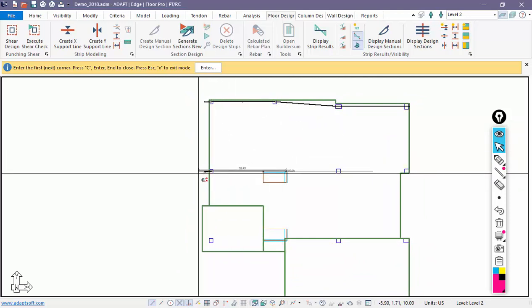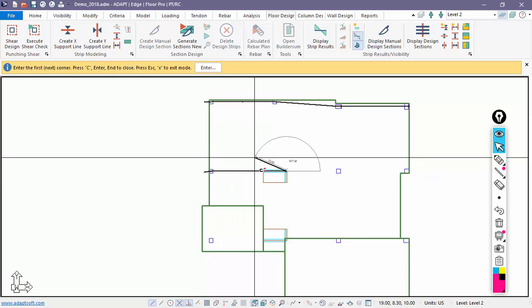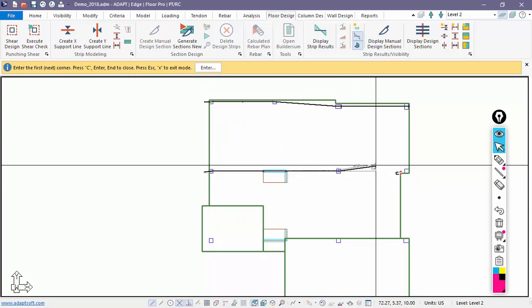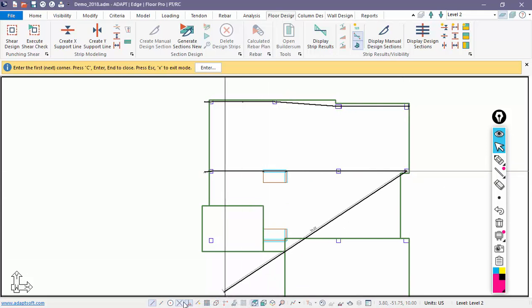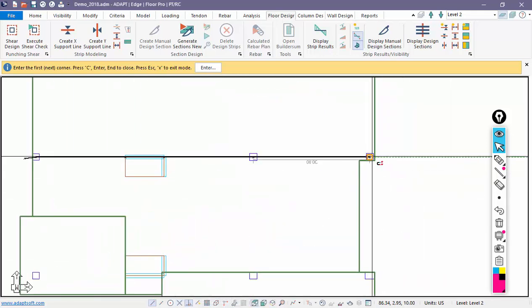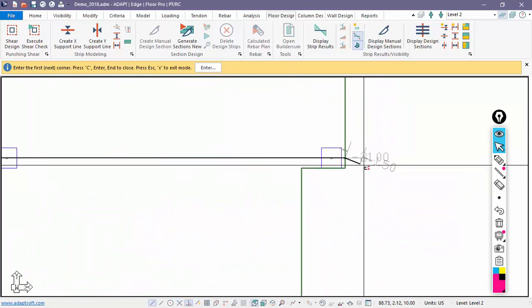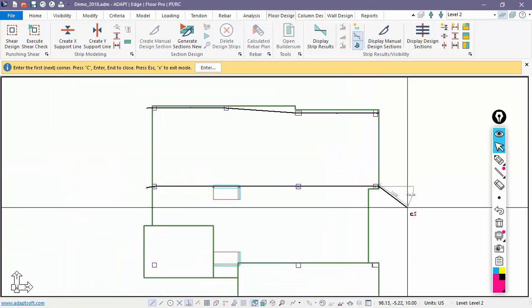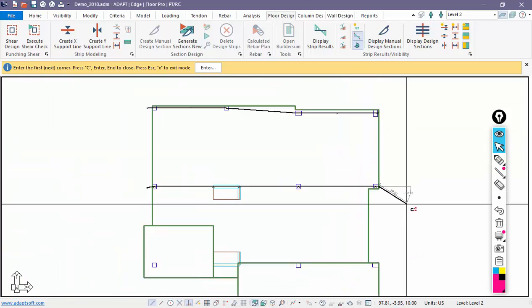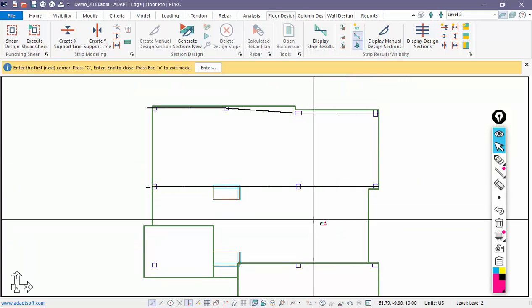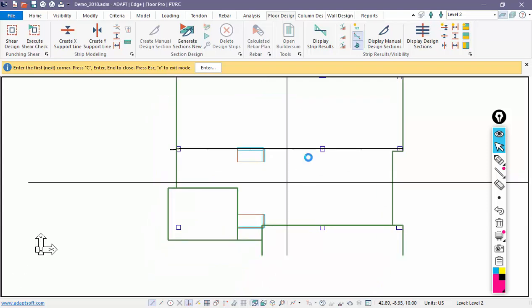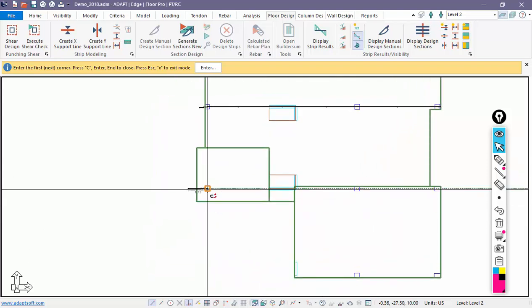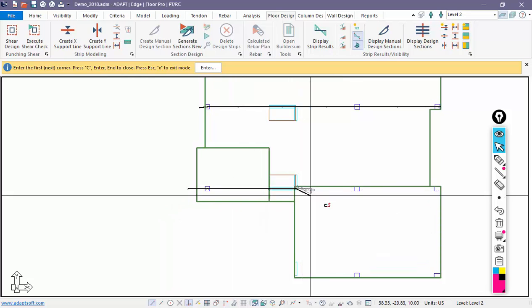We're going to, again, snap outside, click on support, end of wall, support, support. And here I want to turn on snap perpendicular, and we'll zoom in and make sure we snap on the slab edge. Again, I'll press enter to close that. You could right-click close, or you could press enter. Okay, and then the next line will be, again, column to wall endpoint,